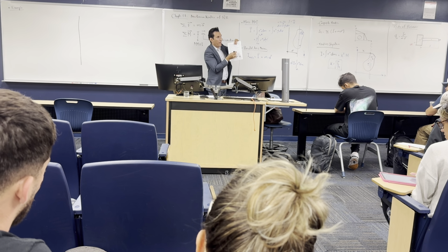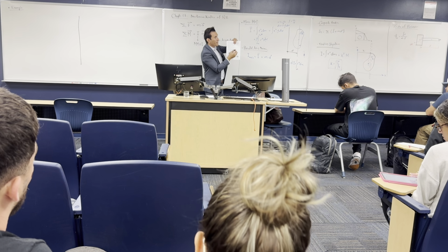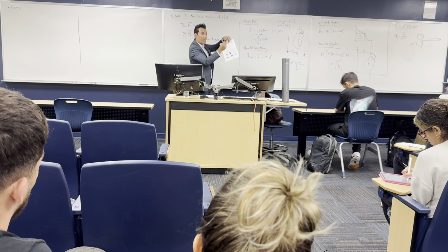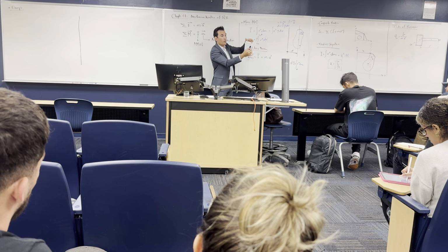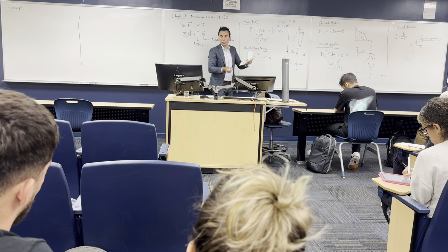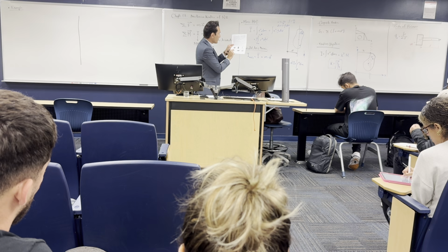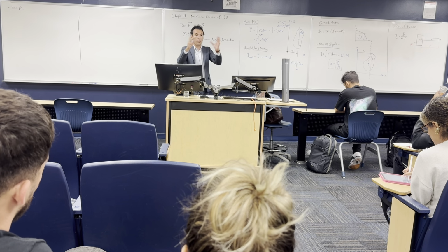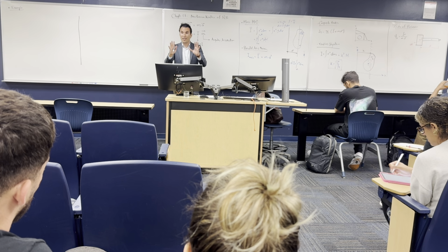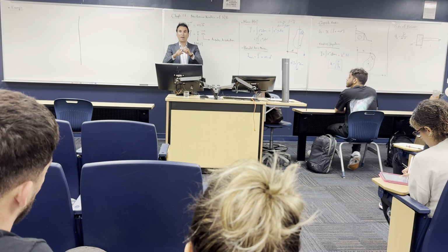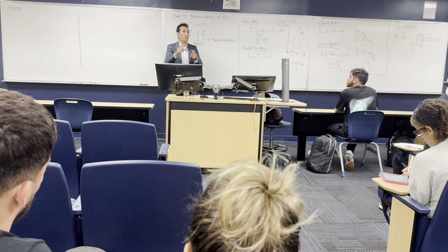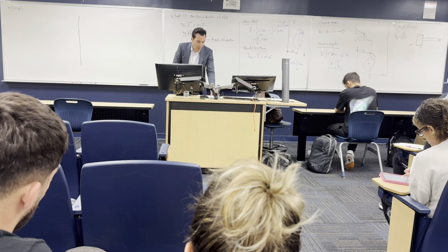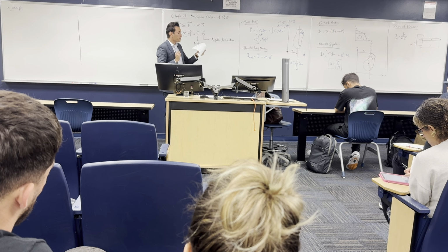If I'm asking about the mass moment of inertia about z, all the masses are measured to the axis that I'm looking at. If it's xy, all the mass is measured about xy. Here, you will find a sphere. For the sphere, like if you have a soccer ball or tennis ball, is it going to be different, the mass moment of inertia about x, y, and z? It's symmetric about all axes. So Ix equals Iy equals Iz, it is the same thing.